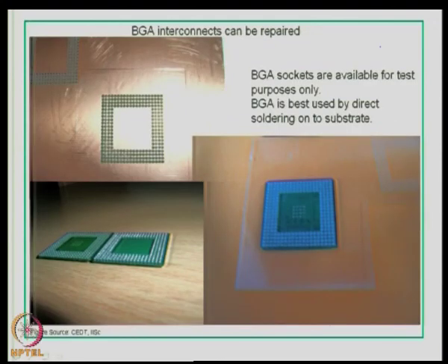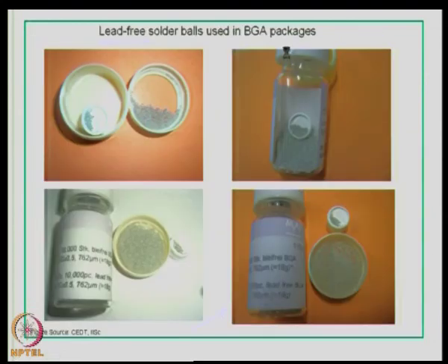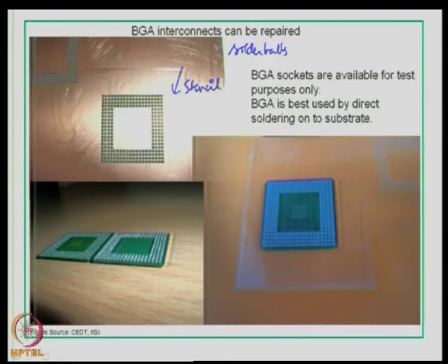If you look at this particular slide, here we have used another stencil again pertaining to the arrangement of the BGA, and the distances are well measured. Here we have used solder balls itself. I have shown you the previous picture of a solder ball. These have been placed on these holes that have been drilled on a thin laminate structure or a thin polyester sheet, like here you can see here, which is used for alignment.